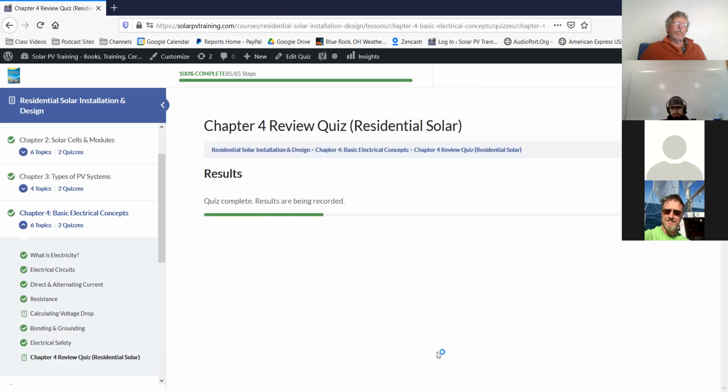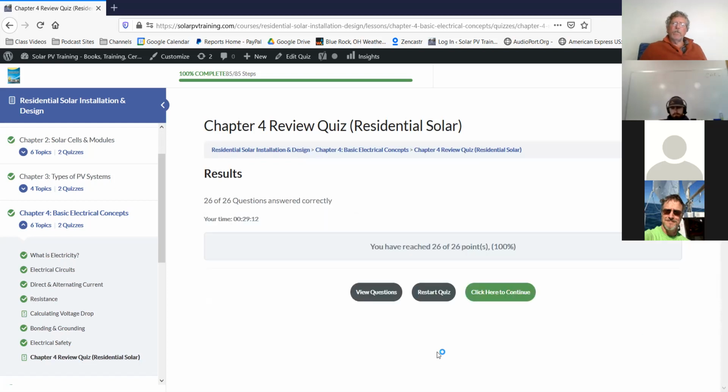So that's taken us through the basic electricity. Just to reiterate, you need to memorize basically the three equations. Watts equals amps times volts. Volts equals amps times resistance, or VIR, that's Ohm's law. And those are just telling you relationships. If you know two of the variables, you can figure out the third. And then you need to know voltage drop, which is basically Ohm's law adjusted for distance. So those three are the big deals.